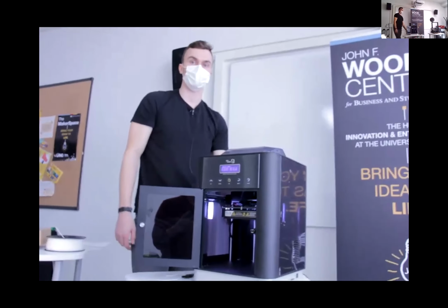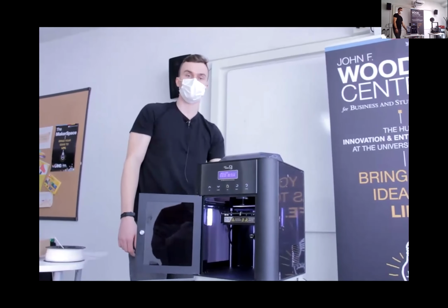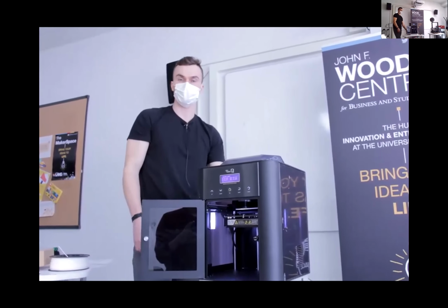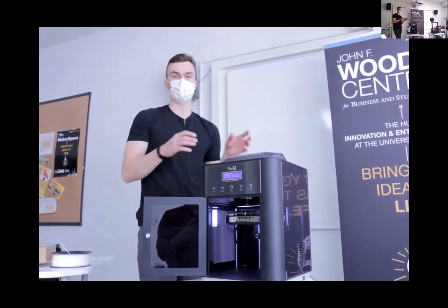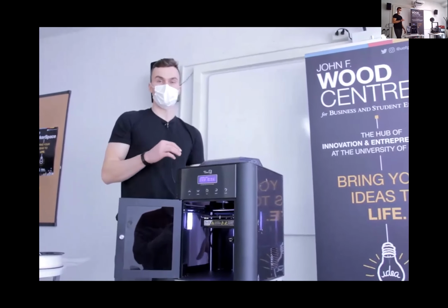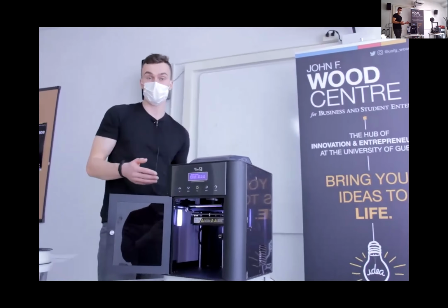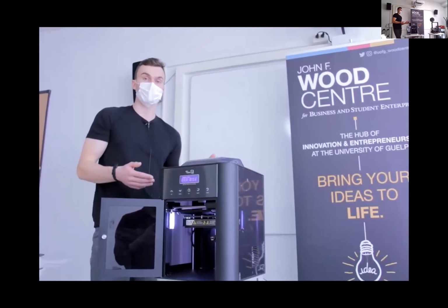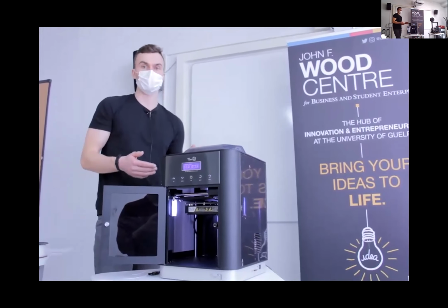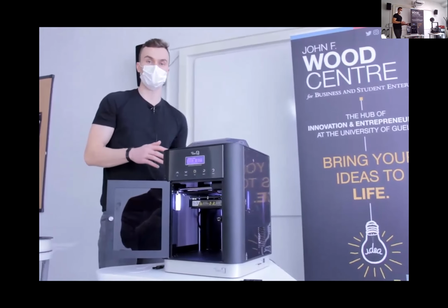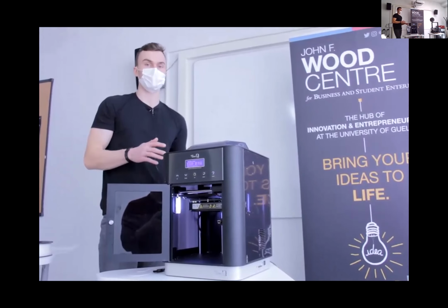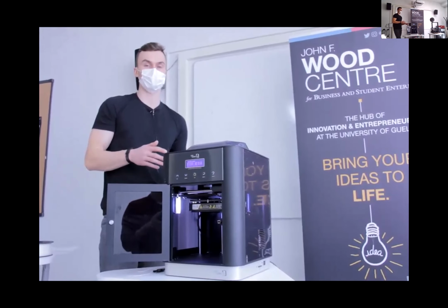A resource I made for the second 3D printing workshop, when we talked about slicing for preparing for the print. So once we had our file, we talked about slicing. In that PowerPoint, I referenced a couple different types of filament and the temperatures that they are printable at. To give you an example, PLA, which is the most common plastic, wants to be printed at around 200, 215 degrees.